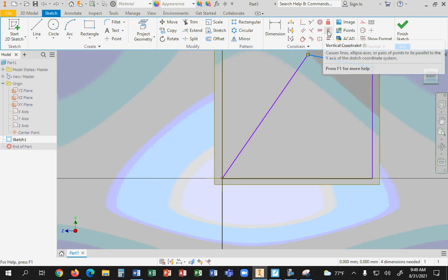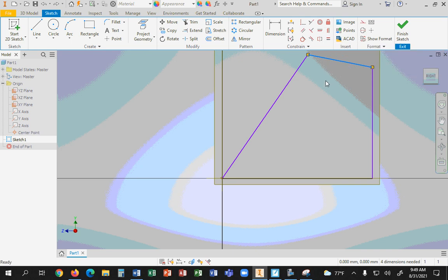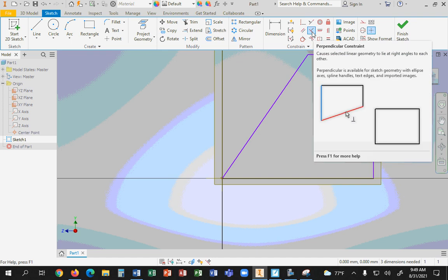It's counterintuitive to what you're trying to do, but this is a 3D parametric modeling product. It doesn't see things the way you think, the way you see it. Got it? I'm just giving you the facts. I'm not trying to mess with you. You got to work with the product the way it is. The other thing you can always do is pick this line like it is, hold down your control key, pick the other line right here, and pick perpendicular. That makes it 90 degrees from each other. Got it? In order to use this command, you got to pick both lines. You can't pick perpendicular to one line because it's perpendicular to what? It can only be perpendicular to another object. Cool?